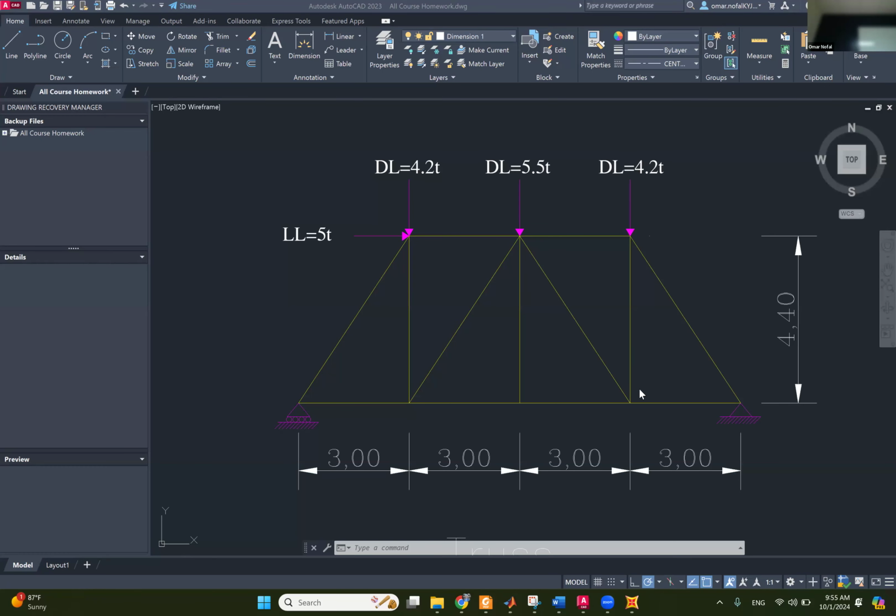Like for example, if this truss is a steel structure, and you have 5.5 ton, that's like 5,500 kilograms, and the own weight of this whole steel truss structure is like, I don't know, let's say 500 kilograms. That's like nothing if you sum all these loads. Like if you sum all these loads, it's almost 1,500 ton, and you have 0.5 ton of the structure, that's a very, very small amount. That's less than even 5% of the total structural load. And you can actually include them in the joint load.